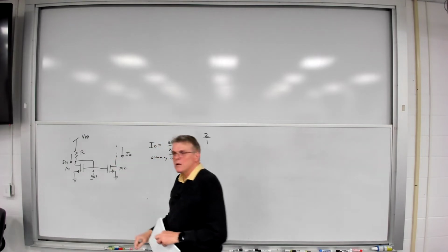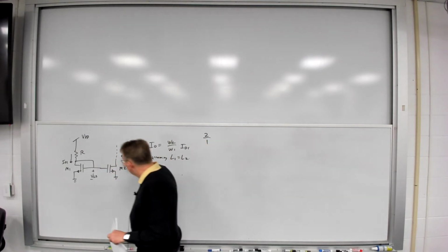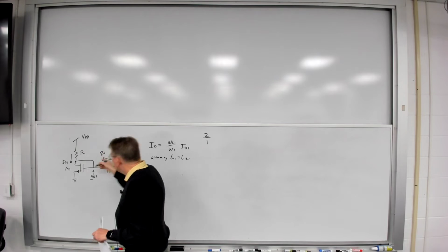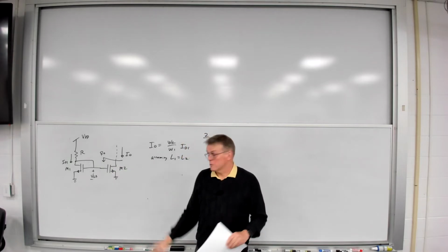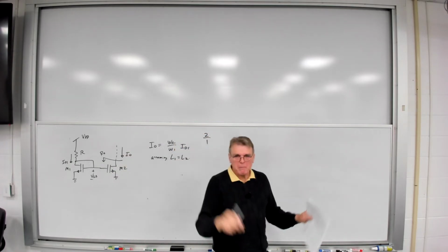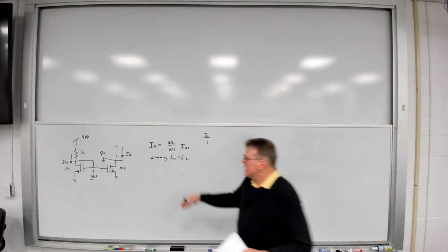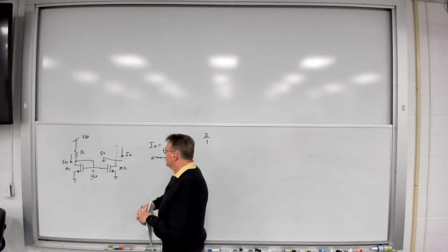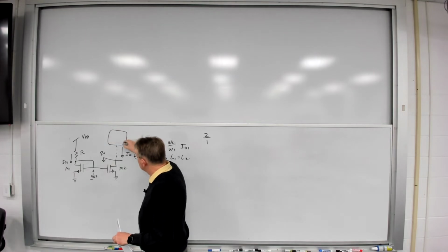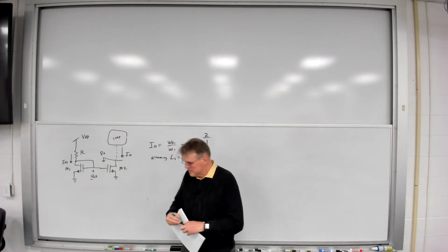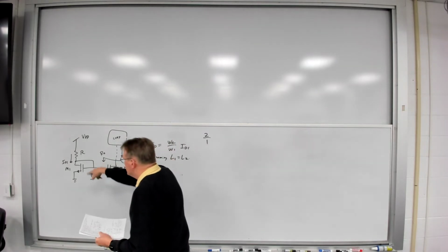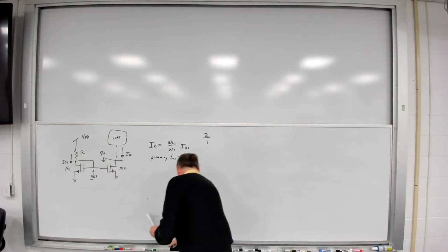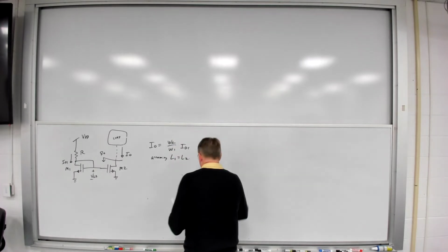Now, we also talked about the performance of this circuit. What is the output resistance of this circuit? This thing is behaving like a current source, or in this case actually a current sink, if you want to be more formal about it. But what is the output resistance seen looking down into M2, given the fact we know it's going to be sinking some kind of current from some sort of load, some amplifier or some other circuit? Well, let's think about this for a moment. If I take this circuit and I convert this to its small signal equivalent, I'll get the following.